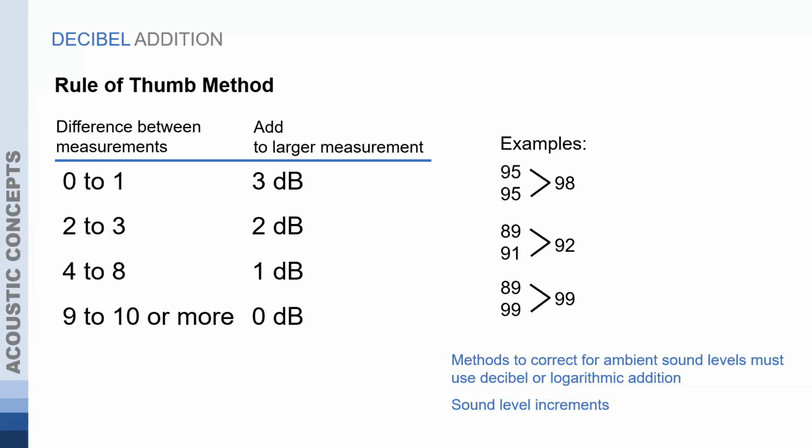is a little bit more specific when you get into different frequency content and all, but the general overall rule of thumb is that if you're about the same level, maybe within a dB, you're going to add together 3 decibels on top of that sound or the louder sound. Now, if we've got two sound sources and the pressure difference between them is 5 decibels, then we're only going to add 1 dB to the higher level.